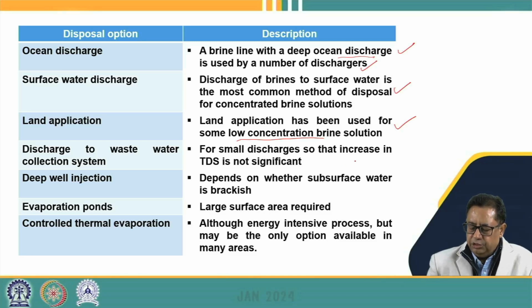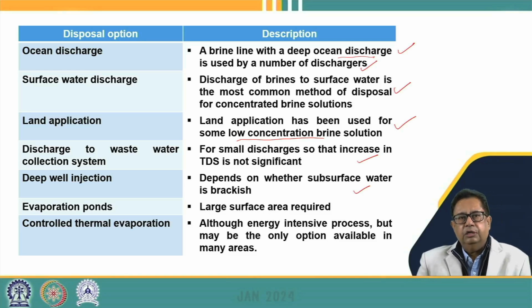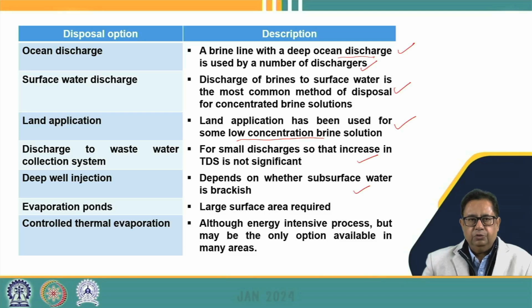Similarly, for small discharges where TDS are not significant, it can be directly put into the wastewater collection systems. It can also be put into sewer lines, but it should not increase the total dissolved solids, TDS, to a significant level. Similarly, we can also think of deep well injection, where the concentrate may be put into deeper aquifers which are not connected to the surface aquifers. There also we have to see that the water does not contain certain types of contaminants.